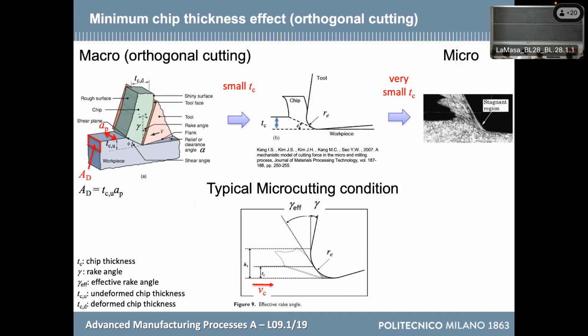You know, in mechanical applications, zero rounding doesn't exist. If you go there with a microscope, you always can measure a radius. In the best cases, where the tool is made of diamond, you could measure 1 micron of rounding. Still, 1 micron exists. The point is that in micro machining, the chip thickness could be of the same order of magnitude as the radius at the cutting edge, because sometimes the chip thickness is just 1 micron or less, or a couple of microns. Okay, so what we are pretending to do is removing a really thin layer of material. But our tool is always dull. It is always rounded, like this.